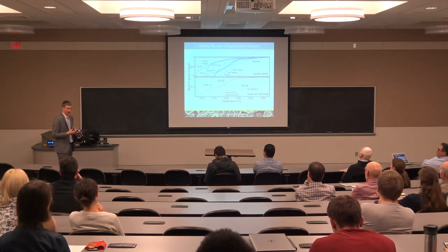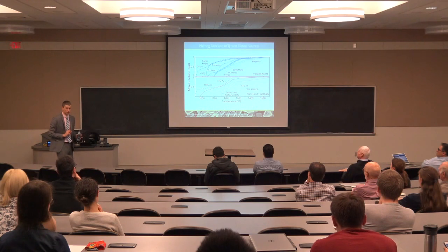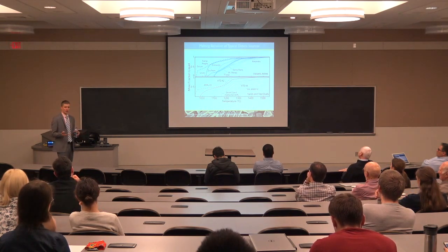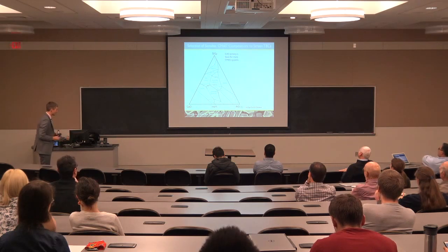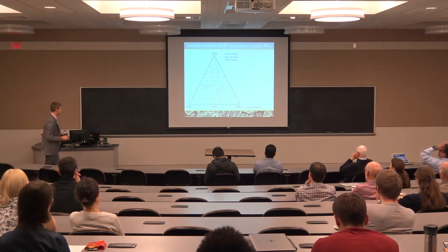And we can also say that since it's the liquid that we really care about, maybe we can just back up and come at the question from a different way. Instead of saying, let's characterize all of these different sources of environmental contamination or debris, we can ask what are the liquids that can actually form regardless of what the debris source is. So if we back up and look at a modified projection of the liquid surface just for the silicate calcium alumina system, these are the components that make up the majority of these deposits.